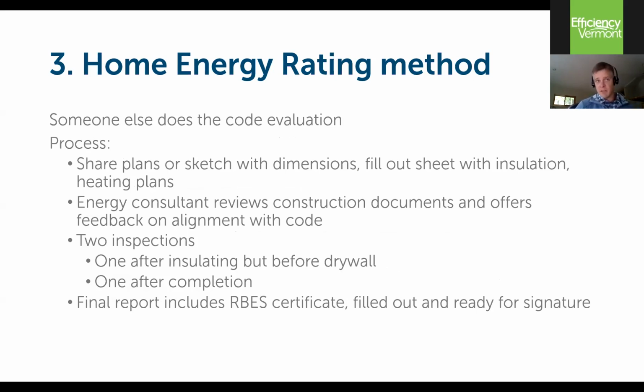A benefit of that is that you get that feedback and you get that understanding of whether or not you're going to comply with the code before you put a hole in the ground, before you even start the construction process. Whereas some of the other methods potentially can leave you till the end to find out if you've met the code or not. It does require that you have that third party do inspections on the building. So it does require that an inspection occurs after insulation is installed and before drywall is put up, and then a final inspection and performance testing upon project completion.